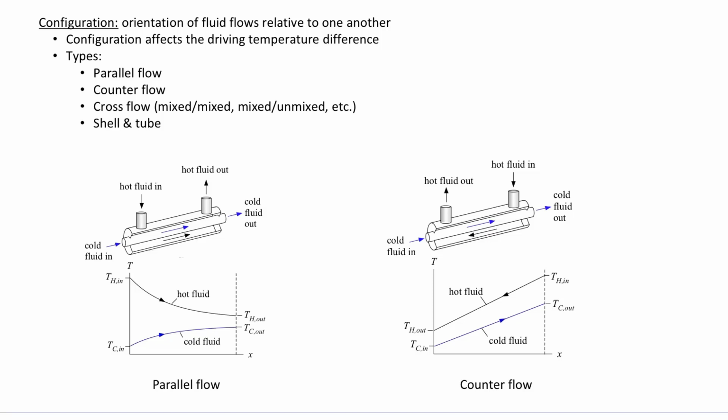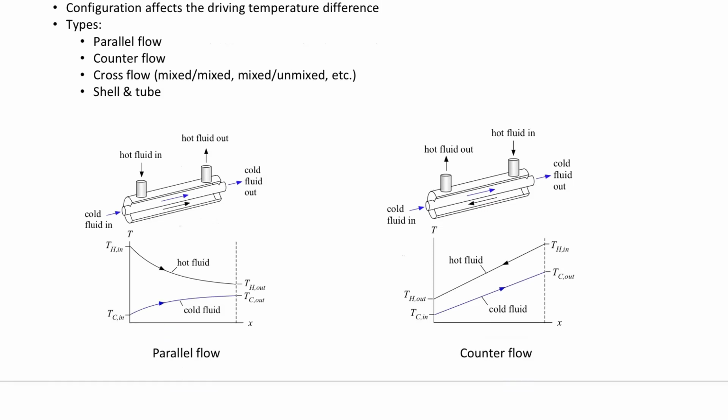So, for example, one way of plumbing up a heat exchanger is shown here, where we have hot fluid coming in on the shell side. Again, this is in the outer region between the outer wall and the inner tube. We have hot fluid coming in here and moving in this direction. I could hook this same device, a tube with another tube inside it, both up, so I have hot coming in on this end, cold coming in on this end, and they're both moving in the same direction. The same system. And the temperature profile for that is going to look something like this.